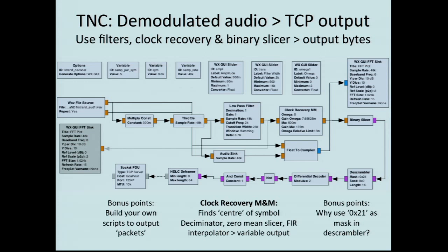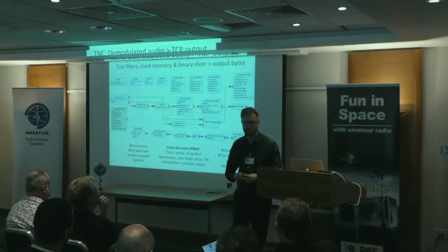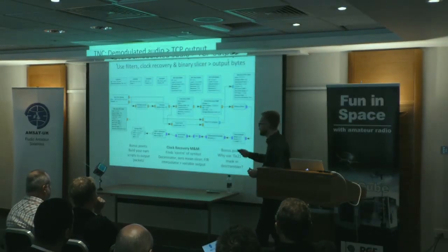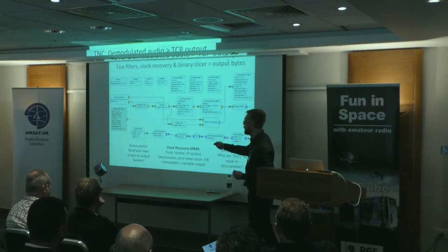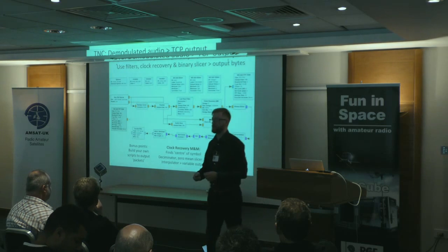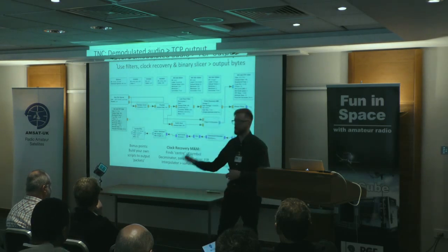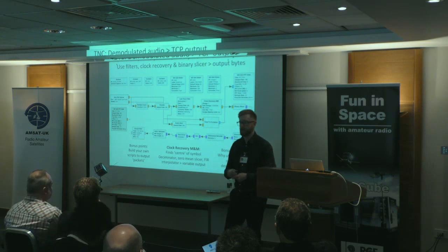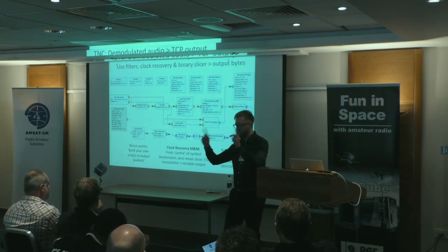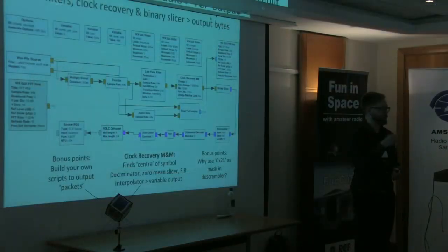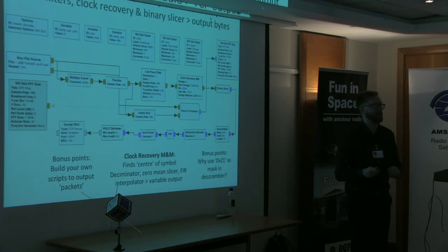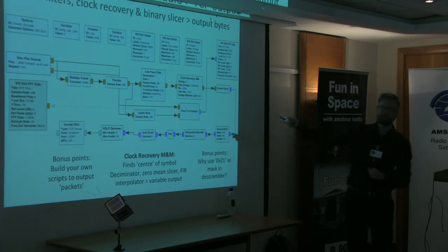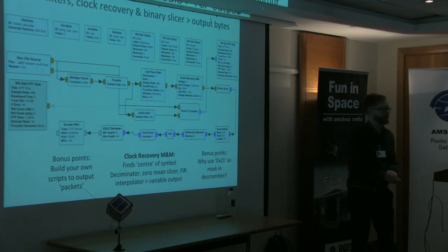Again, the blocks start to look a bit messier. The ones I'm going to show you today are not the ones that would usually go on my course. These are ones that get people into things that aren't as scary, without big scary blocks in them. We're bringing in sources, but in this particular case, I'm using a WAV file. So I can record something in SDR Sharp or GQRX, and then play it back. I can go into Audacity, cut out the bit that I know has a signal in it, and play that over. I can get that working in exactly the way that I want, because remember, you can play with all these variables. All of these variables in here, you can change at runtime.